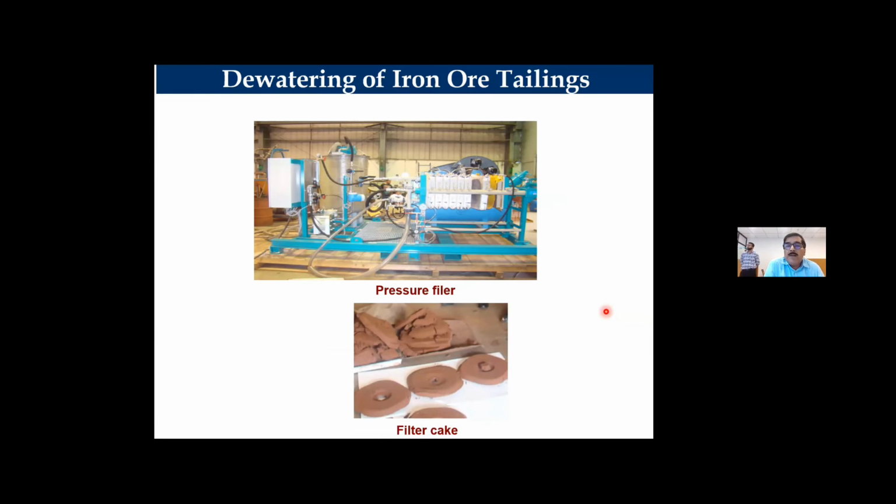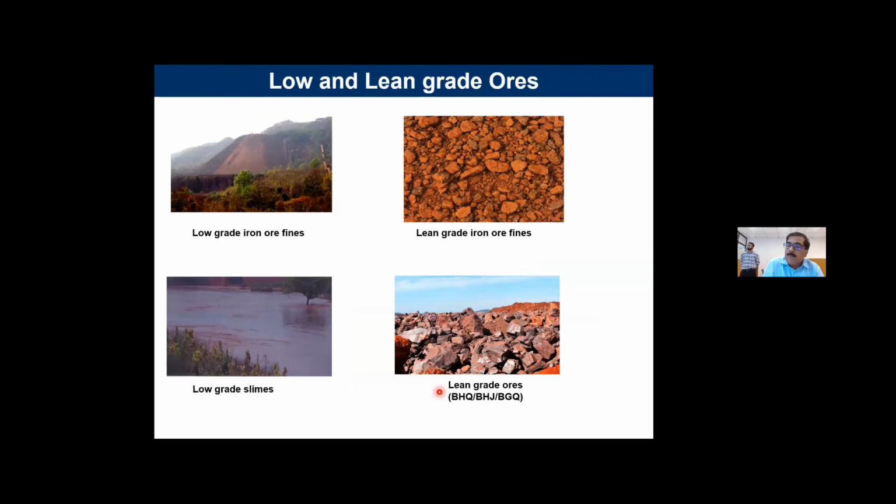The pressure filter, as per present practice, the pressure is maximum, they are going to 12 to 13 bar. But now in my center, we have brought a 20 bar pressure filter at pilot scale to filter and make a cake. The cake you can stockpile at the site, then you can make greenery on those clays. But when you are going below 55 grade, the conventional process which I have shown you may not be economically viable.